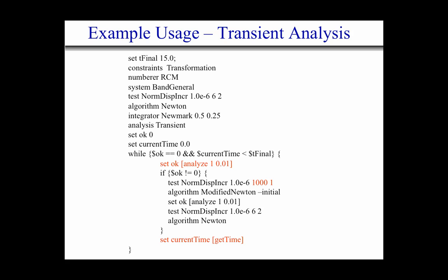Let me go have a look at what the solution is, if there's a big kink in my solution or something going on at that point. Maybe the results after this point are totally meaningless. Up to this point, the results are fine, but after this, when I'm having to turn off convergence, you can turn off convergence for a step or two if you want in OpenSees. So after you turn off convergence or you go to one of these initial iterations, maybe I've just gone on the wrong solution path and, instead of going to San Francisco, I'm going through Oakland or somewhere like that. Okay?